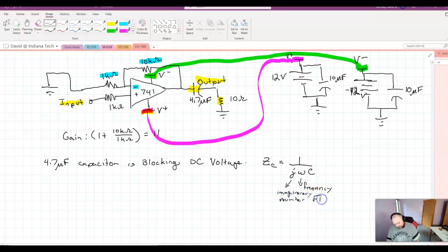Square root of -1. And those of you who've learned about imaginary numbers might say, wait a minute, we use I for imaginary. Well, not in electrical engineering, we use J because I is for current. So we definitely use J for the imaginary number, and C is the capacitance. Without going into too much detail, if you have a low frequency, which technically the frequency of DC is 0, and actually technically a DC signal probably does have some frequency because if there's any kind of ripple voltage, but I'm getting ahead of myself.